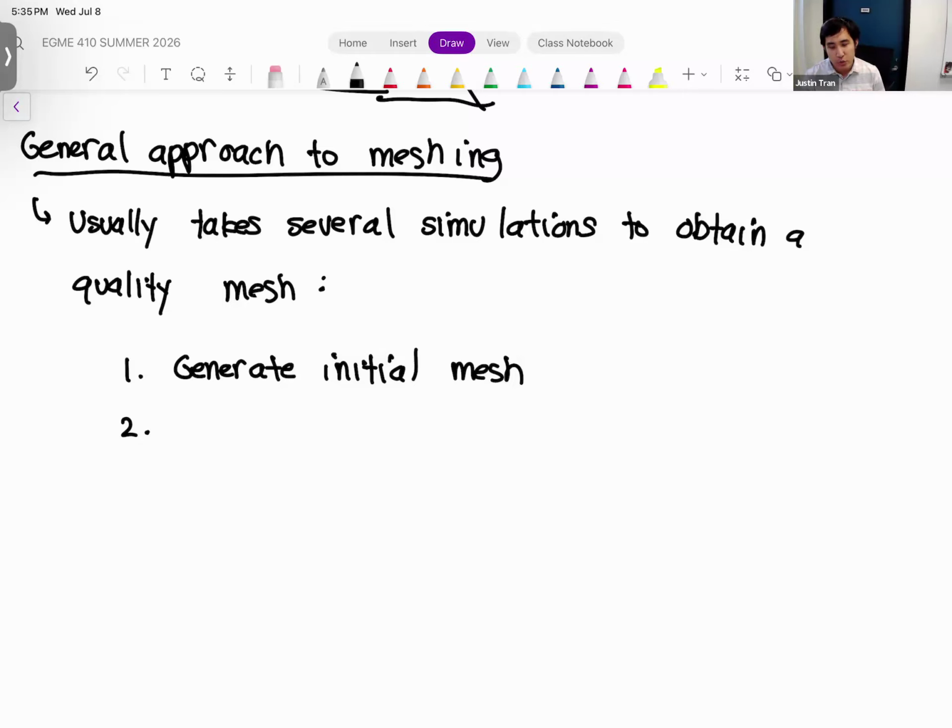There are situations where we want to use 2D elements and even 1D elements, which we call special types of elements: shell and beam elements. We will talk about those early next week on Tuesday. So there are situations where we can change, but it has to be within a certain special case. Okay. All right, so step one, generate your initial mesh, and then from there you can apply your boundary conditions.